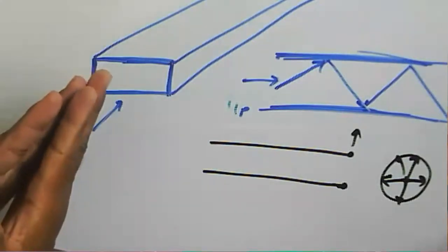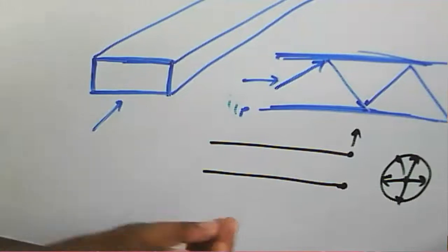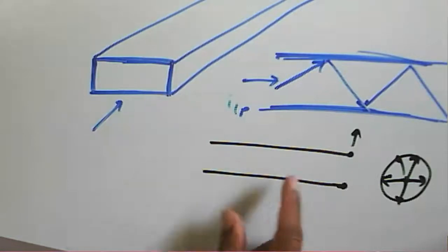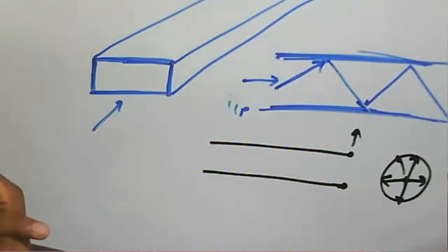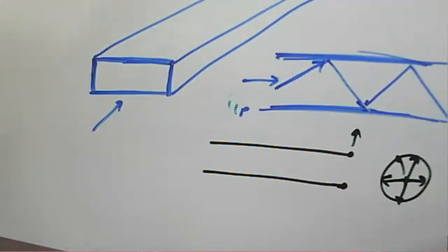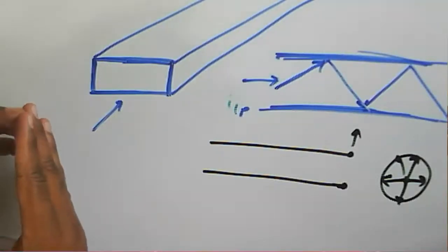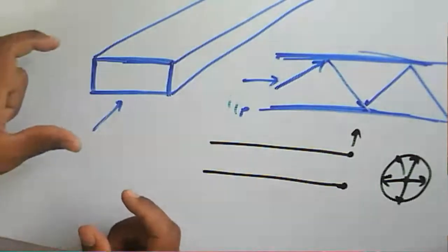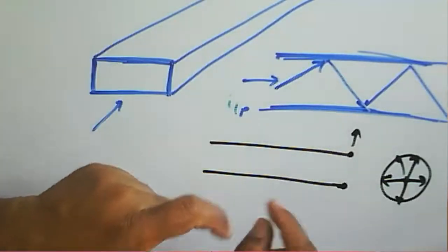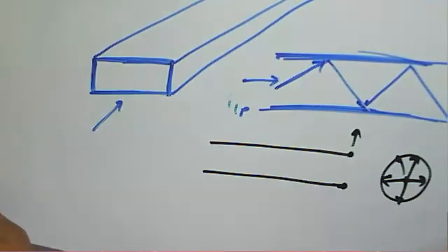what the difference is between a rectangular waveguide and a coaxial cable or a two-wire line. In a transmission line, the signal propagates through the wire as an electrical signal. Even a coaxial cable, which is nothing but a two-wire line, carries the signal through the wire. But in a rectangular waveguide, the signal propagates in the form of a wave, instead of a current.